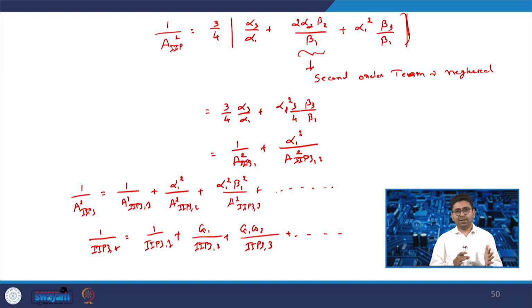And when we consider the noise figure, the first component is important. So, for receiver design, for noise figure you should consider the first component, and for IIP3 you should consider the last component. But it is not always true, because we will also see one example: if your certain stage does not provide sufficient IIP3, then your signal will be distorted.